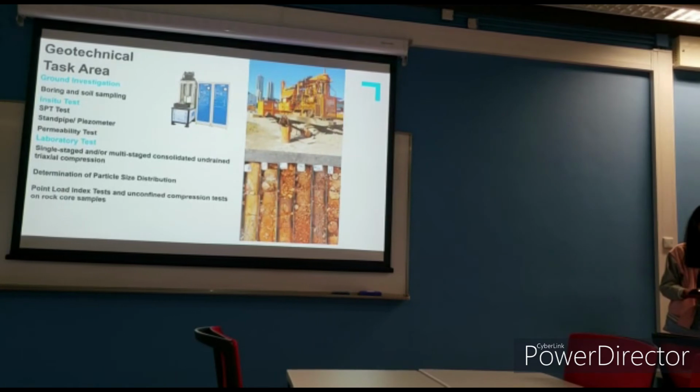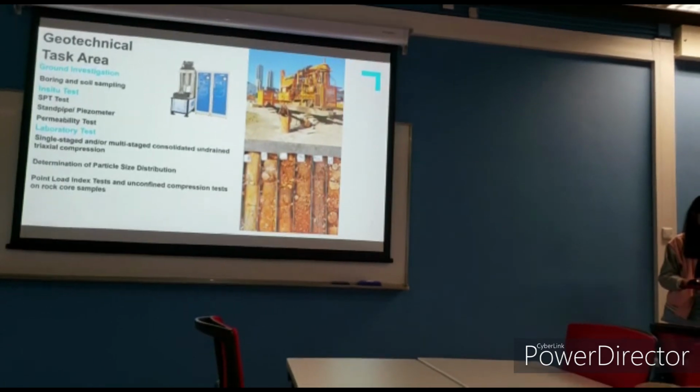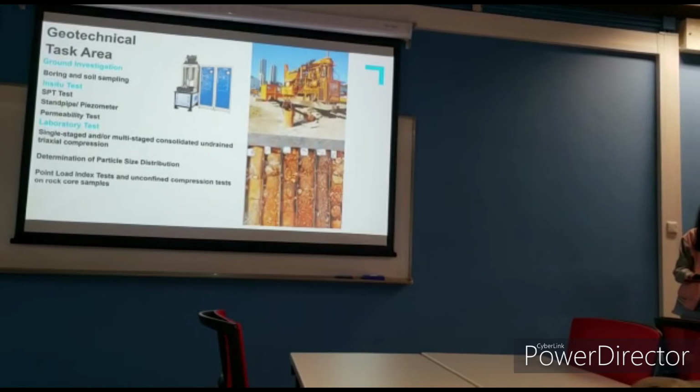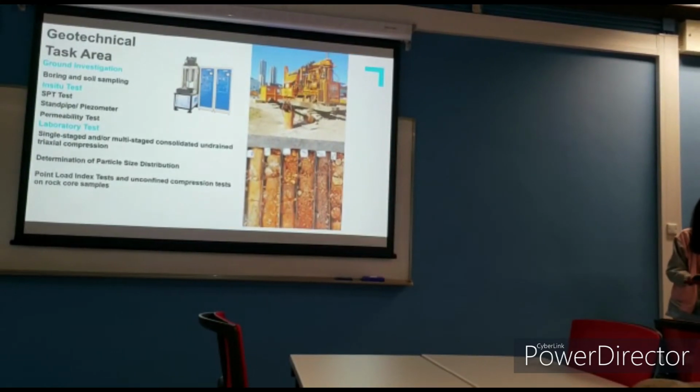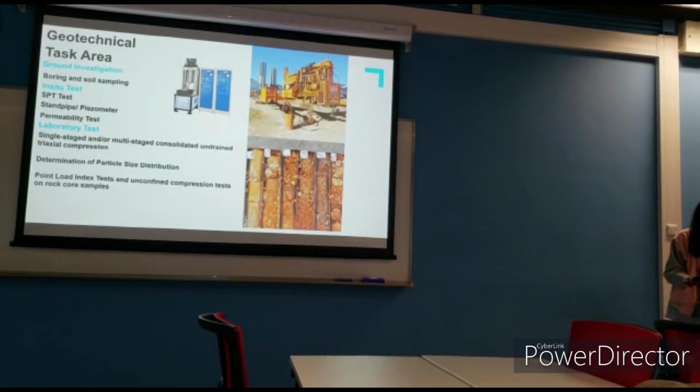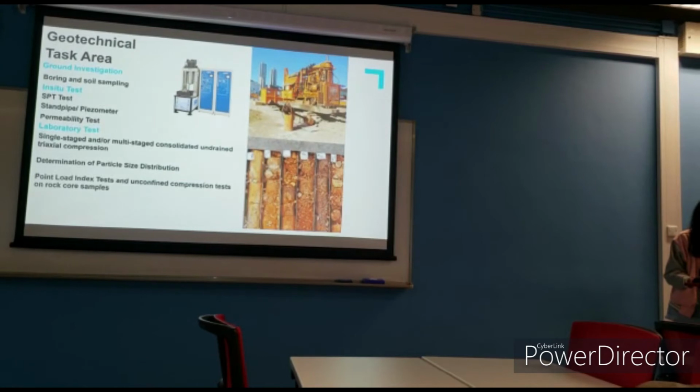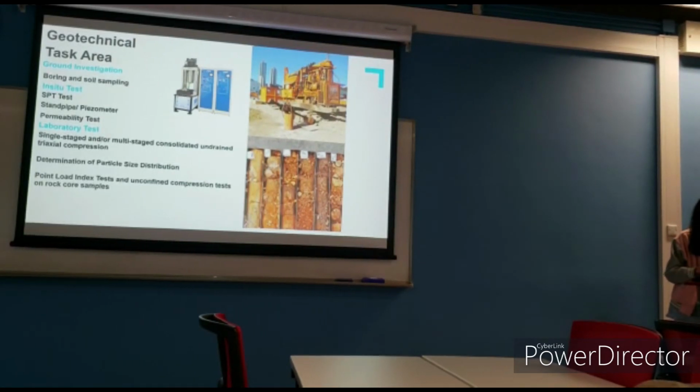For the vertical borehole, sampling is at a 2 meter interval each. Also, a piezometer or standpipe should be installed to verify the groundwater condition. Also, we should carry out the permeability test to verify the permeability parameter of the soil.